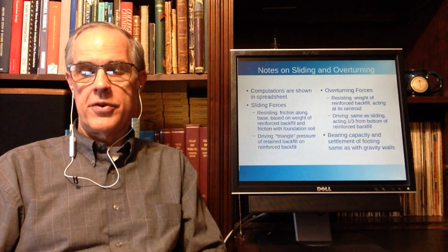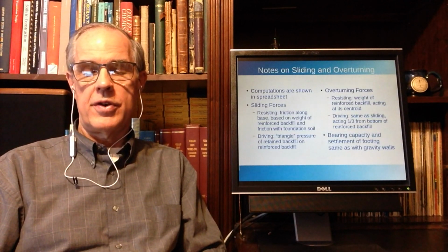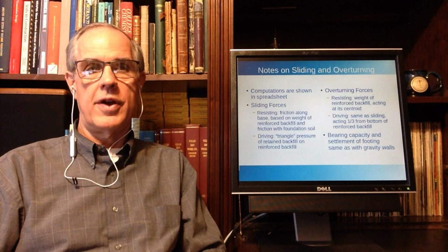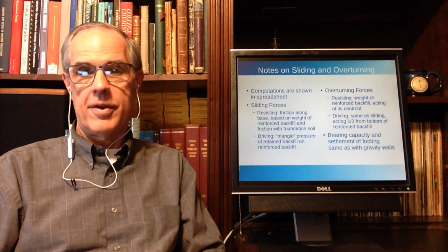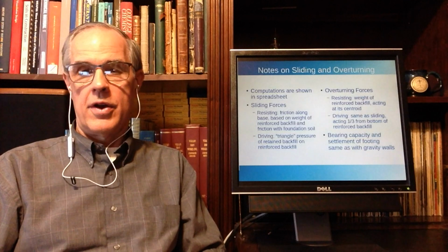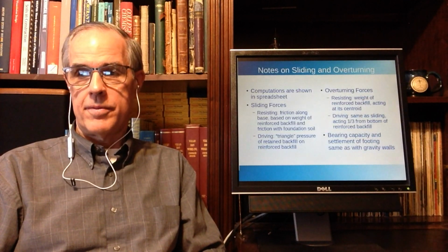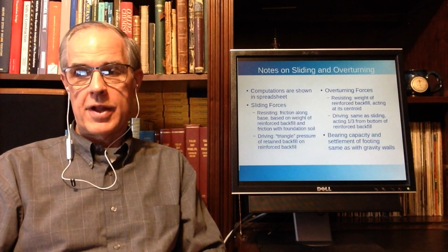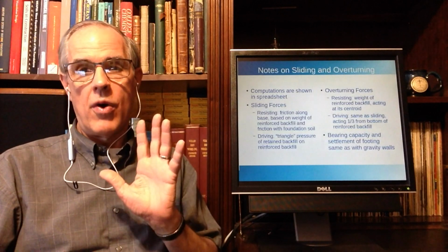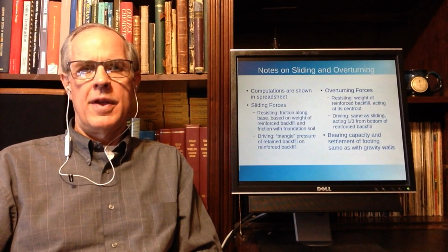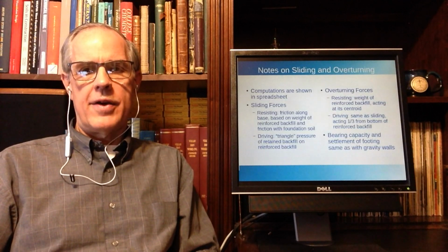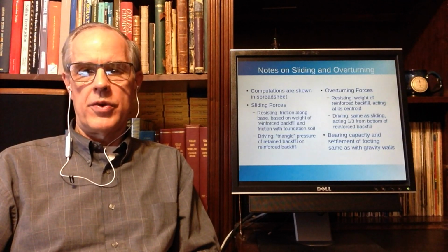The sliding forces are simply based on the friction, on the driving force of the retained backfill versus the friction of the bottom, what I mentioned before. Overturning forces are as I've also mentioned before. And bearing capacity and settlement of the footing, and for that matter the whole wall, is the same as a gravity wall.